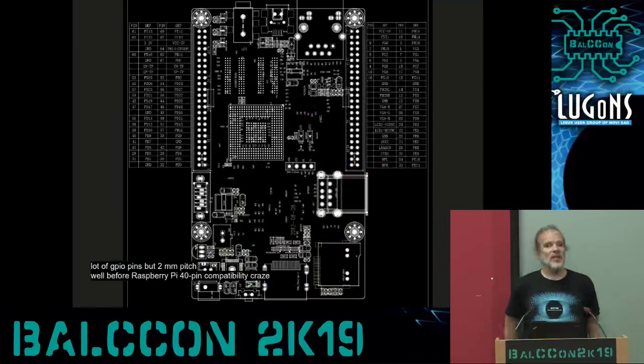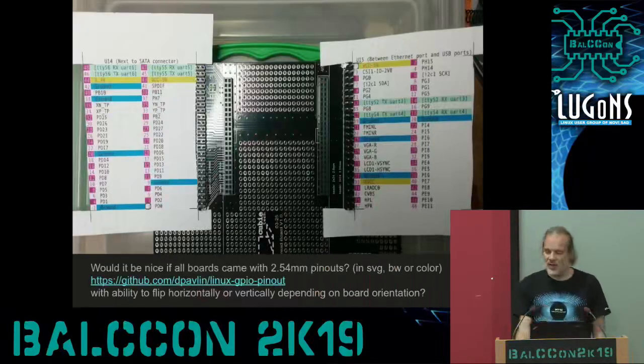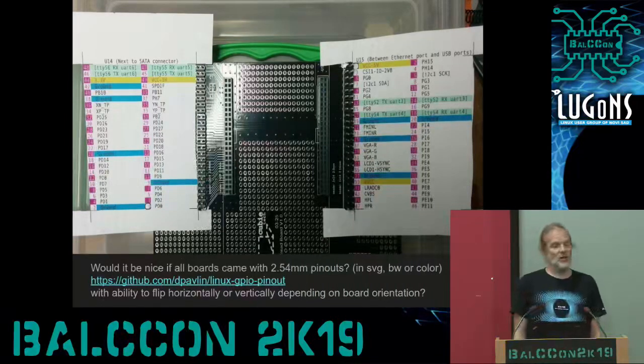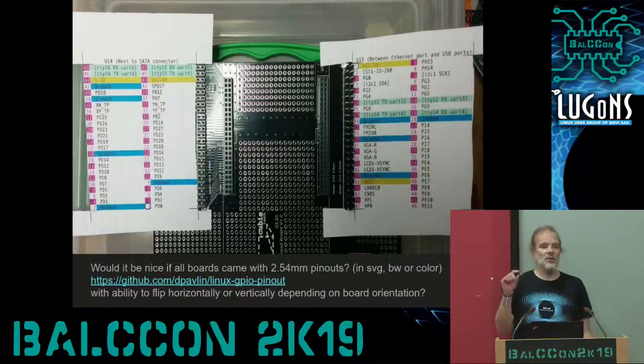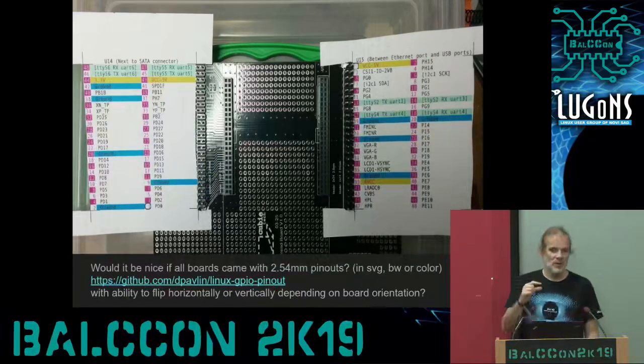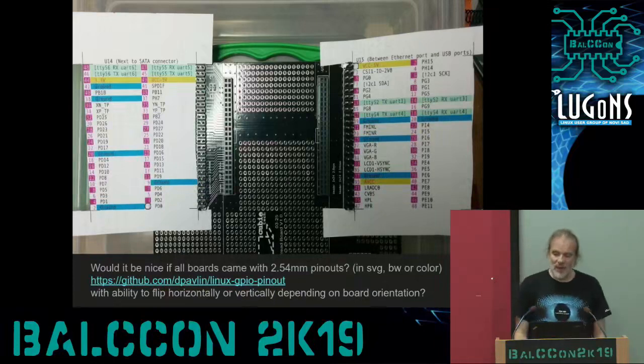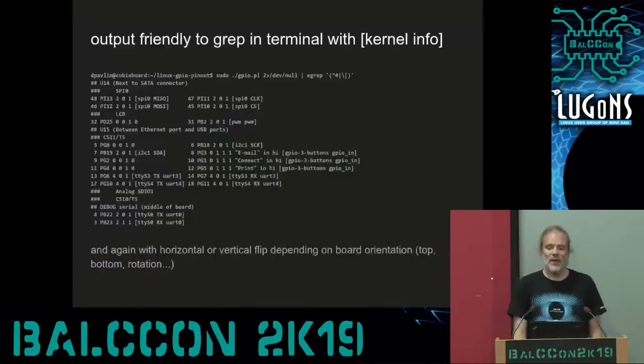Since this board was created before the Raspberry Pi 40-pin connector craze, it has a lot of pins, but unfortunately they are all in 2mm pin pitch. So another project which I found incredibly useful was the script which enabled me to print out paper templates in perfect 2.54 millimeter pin pitch, just like the connector on this breakout board, which converts 2 millimeter to 2.54. And I found it very, very useful.